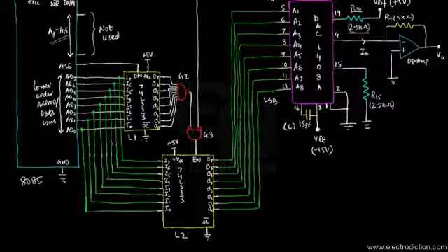Now the latch chip, that is L2, connected with the 1408A. Over there we can basically see that the output of the latch just joins in with the binary input of the DAC chip. On the other hand, we can see that the data coming from the 8085 joins with the input lines of the latch chip L2.